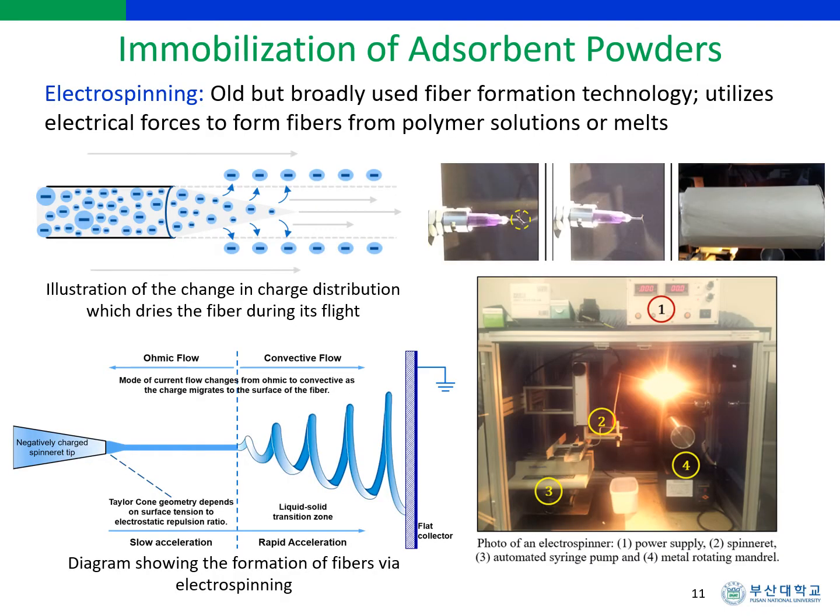Per my first lecture, electrospinning is a simple, readily available, effective, and widely used technique to transform polymer solutions or melts into nanofibers with an average fiber diameter of less than 1 micrometer, or within the fiber diameter range of 50 to 500 nanometers. By fine-tuning the electrospinning parameters, PAN nanofibers with a desired morphology can be fabricated.